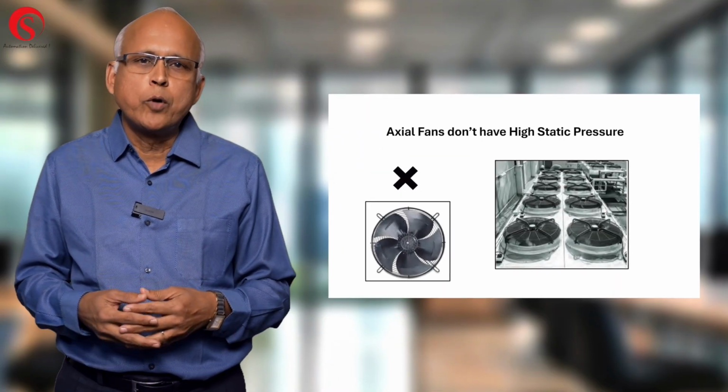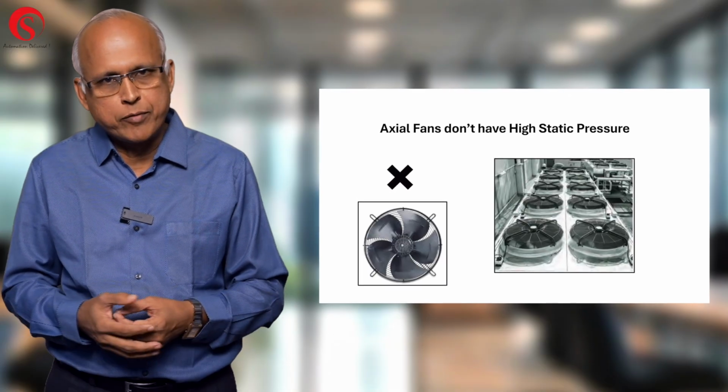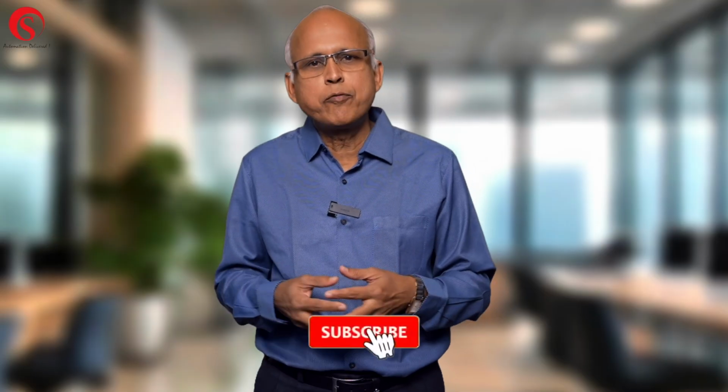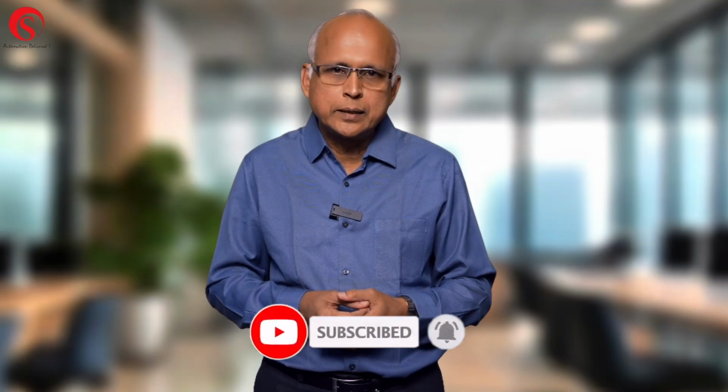Now, if it is an existing air to water heat pump supplied long ago without any discussion with the heat pump manufacturer, we cannot simply put a duct and run it to any cabin. The reason is that an air to water heat pump normally utilizes an axial fan, one or multiple, depending on the design. The axial fan characteristic is such that it generates lesser static pressure and more air volume flow rate. That is why axial fans are used there.